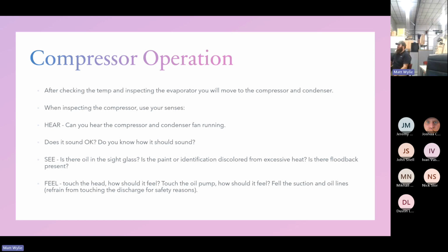I was just looking at 3. I don't know if 3-phase has a rule of thumb or not. It's just you hope there's resistance between each leg and you hope they're all open to ground. 3 phases, they're all equal. They should be equal. If they're not, then you have a problem, right? Yeah. Then it's gonna run like garbage.